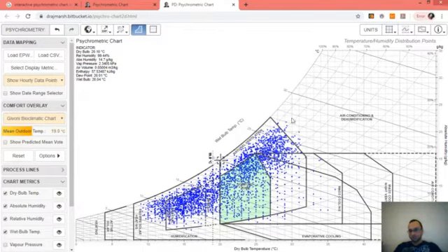There is a number of hours where mechanical air conditioning is needed for sure, and evaporative cooling for some time could be used. We know that similar to Larnaca, Beirut climate is a humid climate, so evaporative cooling use is quite limited.